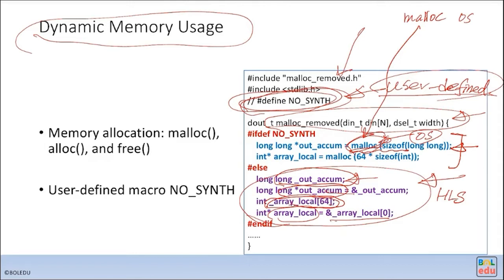The data may have to be stored on the hard disk. So for sure, you could not allocate that much memory statically in an FPGA. So for doing the C simulation, you want to be able to handle a bigger amount of data, so you have to use malloc.